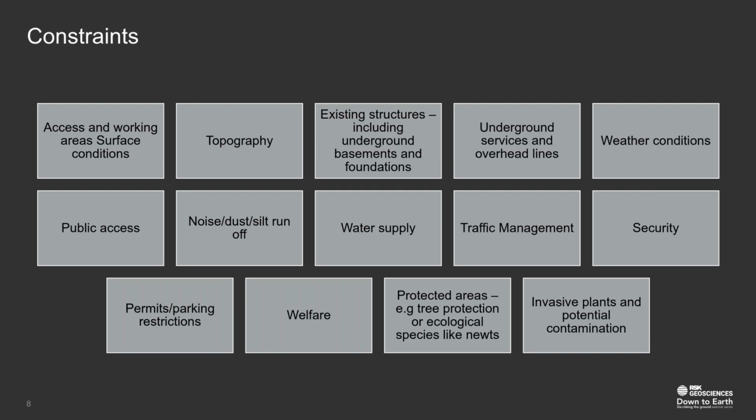Topography. I mentioned this earlier. Are there any steep slopes that are going to cause difficulty getting your machinery into the right place? Are there any existing structures, including underground basements and foundations, that perhaps you can't get to, or you need to have a look at their current makeup? Are there any underground services or overhead lines that you need to be aware of so that you don't affect or hit these services? What are the predicted weather conditions for when you're going to be there?